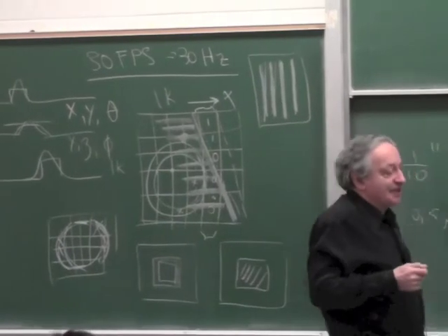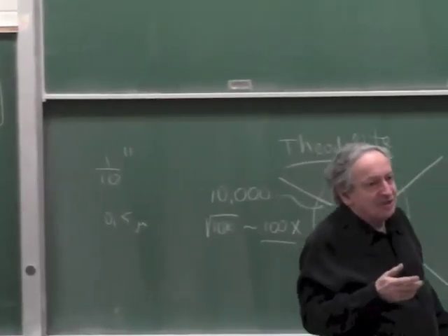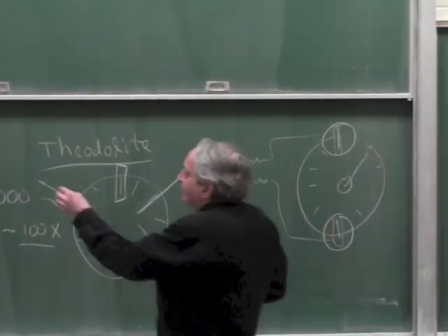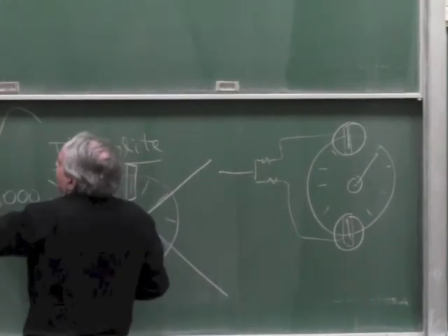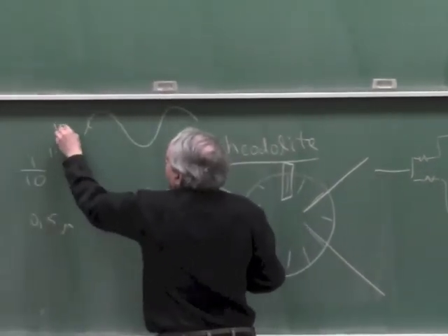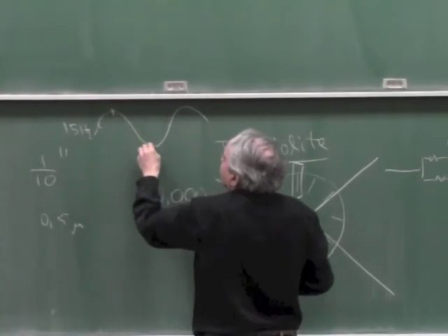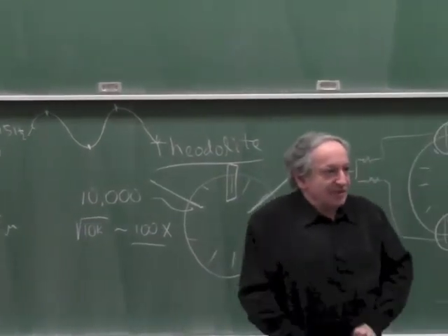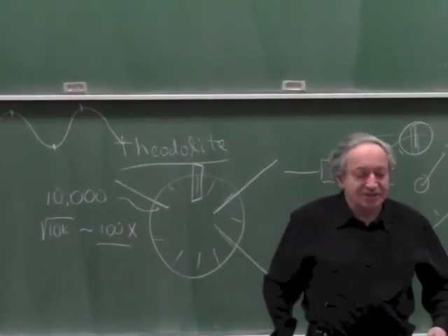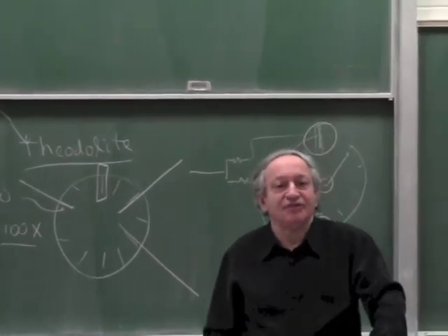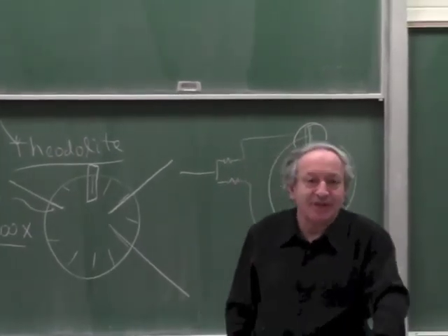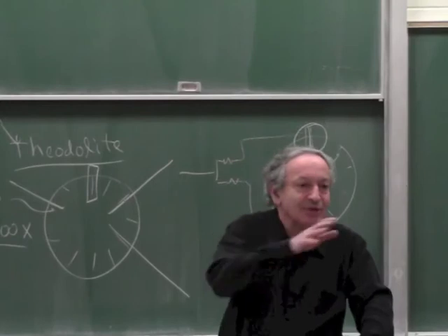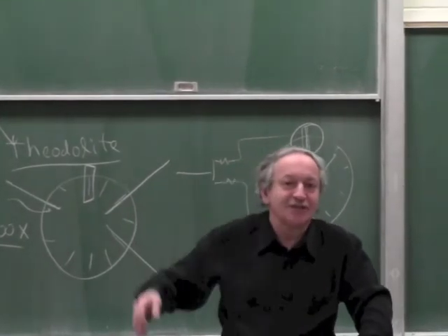because of the Nyquist rate, it means it can only pass information at 15 hertz. Because if you have a sine wave, we went through that already several times, you have a sine wave, and that sine wave is 15 hertz, you have to sample it at least twice per cycle to recover it. That's what's called sampling theory. And therefore, a camera which is 30 hertz, its bandwidth is only 15 hertz, and 15 hertz is very bad because there's lots of things in the room which change at the rate of 15 hertz. Anybody moving, shadows, projectors, light changes.